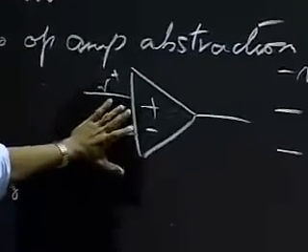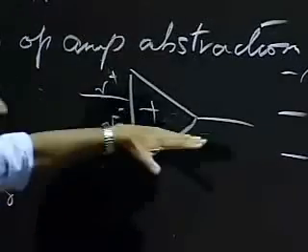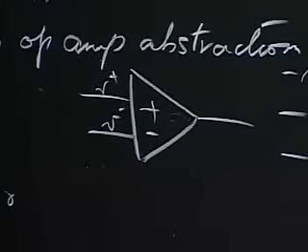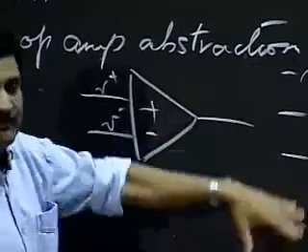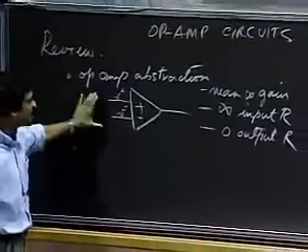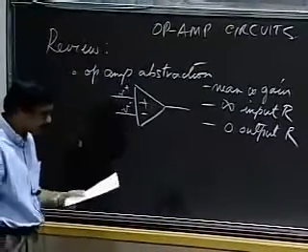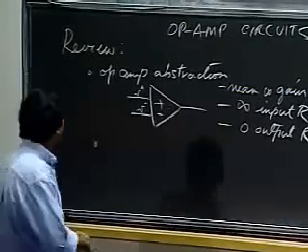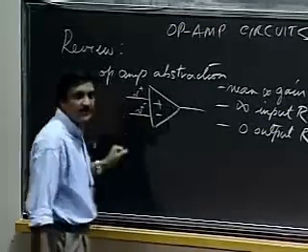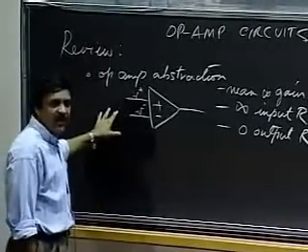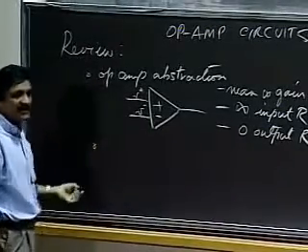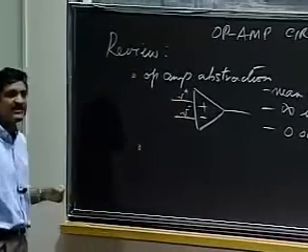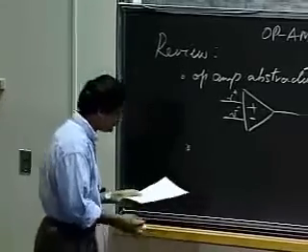To some extent, you have to think about that with the op-amp too, because if the output hits the positive rail or negative rail, it isn't going to behave like you expect it to. But fundamentally, with this primitive model, with this ideal model, it becomes really simple to build circuits with the op-amp. So therefore, it's become a key building block for circuits. So when circuit designers build analog circuits, very often their primitive building blocks are really an amplifier of this sort, an op-amp, resistors, capacitors, and some of our other primitive building elements.